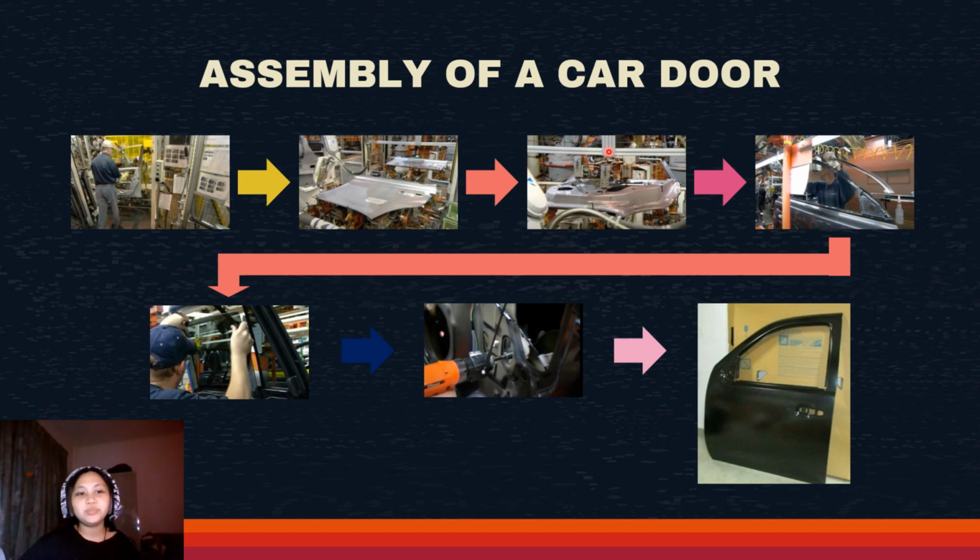A special press then folds the lip of the outer panel over the inner panel afterwards, joining the car door panel together, as you can see in the third picture. This hemming gives the assembled car door another edge. Subsequently, the car door undergoes rust-proofing, paint, and other protective treatment before adding a chrome trim clipped in place on top of the joint panels.